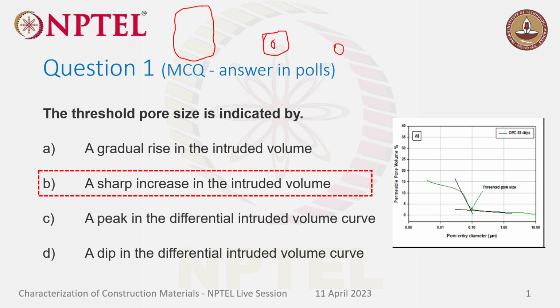If you take the core area, drying is not possible from there. Concrete has to dry first, and it will dry from the outside, not from the inner portion. Normally we say the outer portion is subjected to chemical attacks and other chemical intrusion, so the outer part controls the durability, and mostly the inner portion will not be subjected to drying or other disadvantages that we face from the outer side of the cube.